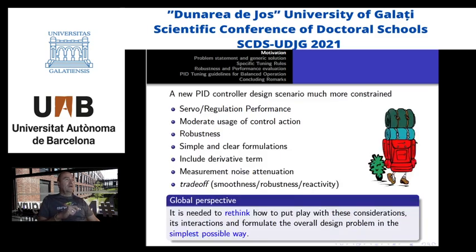Okay. So finally today, the PID scenario is much more constrained than the one that Ziegler and Nichols had 80 years ago. And this is somewhat natural because systems have continuously been asked for more and more. So now we are asking a control system to behave well both for set point tracking and regulation for load disturbance. You will be asked for robustness. You will be asked for as simple as possible a formulation for the tuning. You will be asked for a trade-off among all these actions, measurement noise, etc.